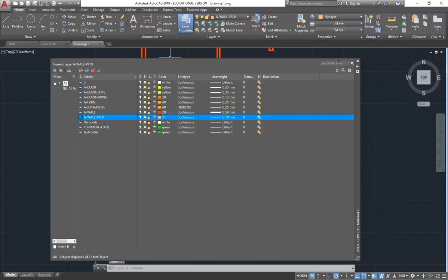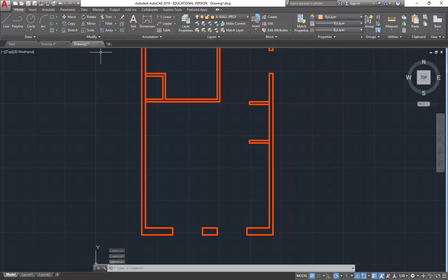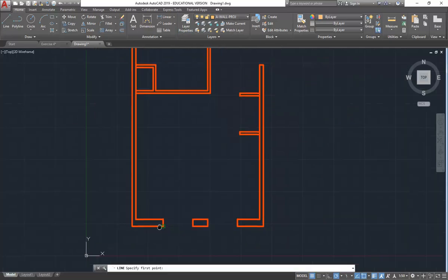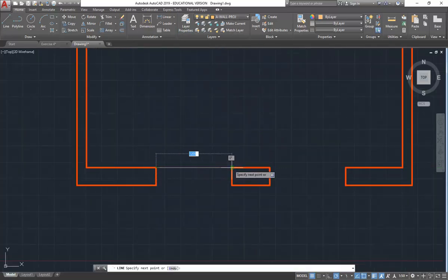Okay, so I'll make that the current layer, and then I'm simply going to draw some extra lines now on that new layer that have my nice light line weight connecting those corner points. And how much better does that read already? Yeah, that's it. Right, so we can tell what's being cut.